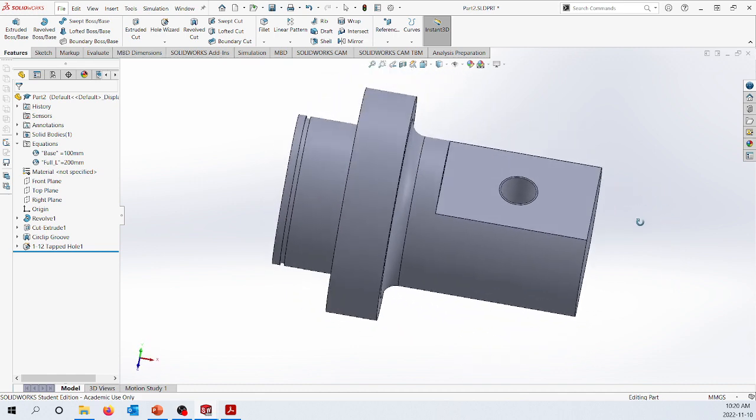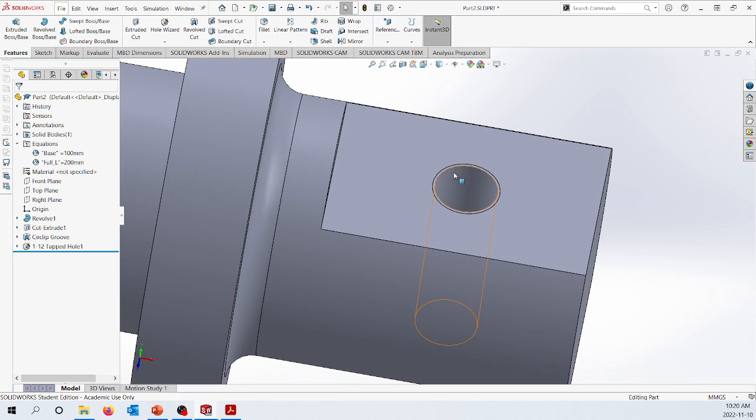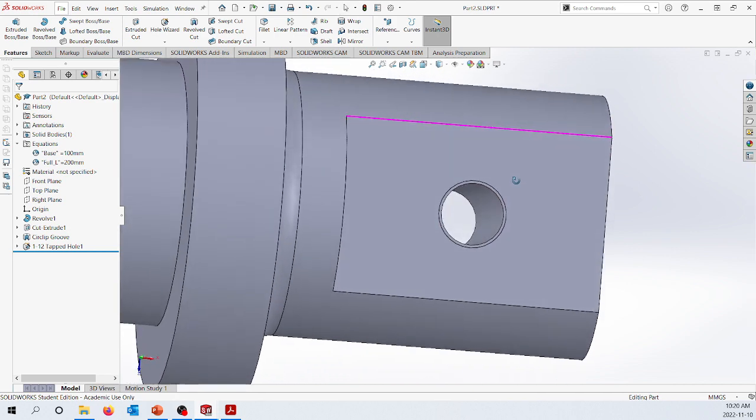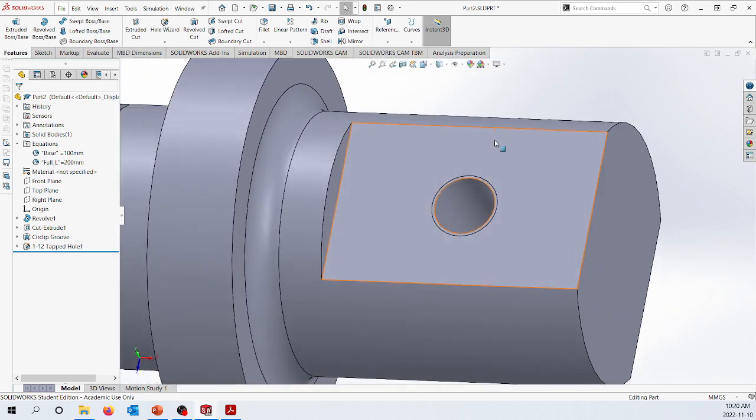So the settings that I have on mine are pretty basic. It's not rendering the threads here, but you can see we've got an inner hole and an inner ring and an outer ring. That's telling me this is a threaded hole. It's just letting me know, hey, this inner ring is the through hole diameter, and then that outer ring is your major diameter of your threads.